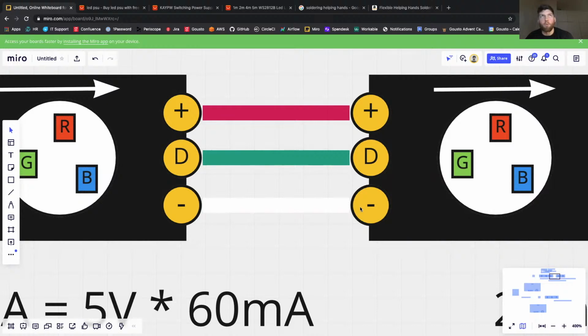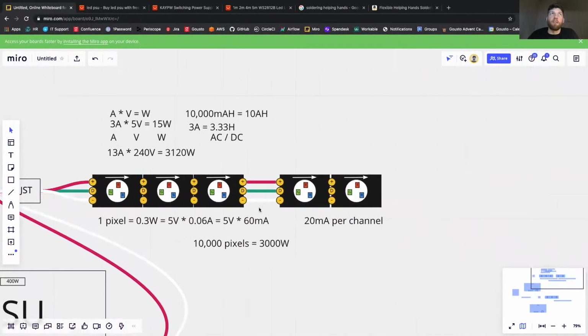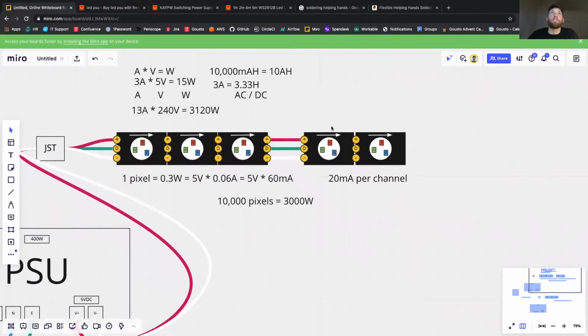Now, I have discovered over time that the best methodology for doing this is actually to place the tip of the soldering iron underneath the pad and then hold the solder spool on top of the pad, and the soldering iron will heat up the pad from beneath and make the pad itself hot enough to melt the solder spool, which will then bead up onto this copper pad and eventually melt. So that is the pro tip for soldering LEDs together. Most of your soldering can be avoided with good project design.